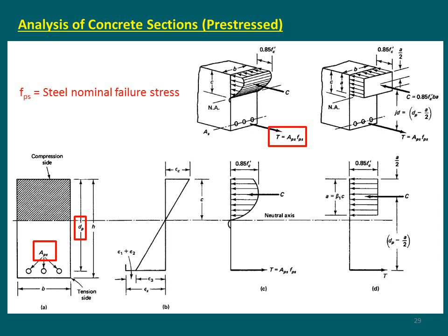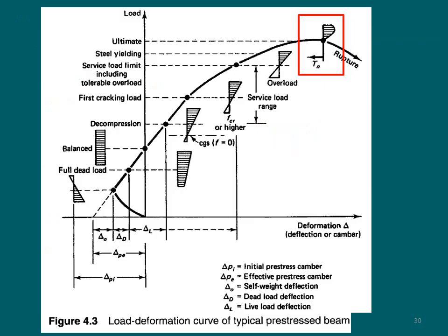In our example, we're going to have two tension forces, because I have here the prestress and also I have the reinforcing bars. And both of them are going to be at the bottom of the section, right in the middle of the concrete beam. So this is going to be the point that we need to work on. The point is at the capacity point. I don't like to call it failure because this is actually the capacity point.